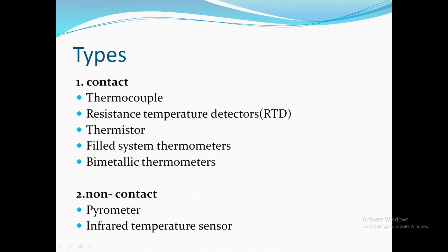Contact temperature sensors essentially measure their own temperature at any given time. They do this by creating a thermal equilibrium between the sensor and the substance being measured. Thermal equilibrium simply means that the two bodies have no heat flowing between them and are hence at the same temperature. There are, however, a variety of errors that can occur while using this type of sensor. For instance, surfaces are especially hard to measure with contact sensors. Contact sensors are by far the norm for temperature measurement in science and industry.